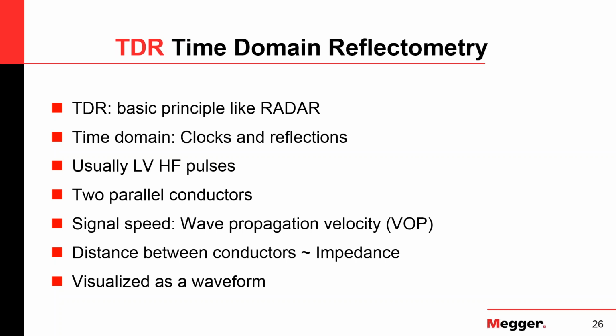So the TDR, by sending down those high frequency signals, will give you an impedance fingerprint of the cable with a low voltage measurement. And today's TDRs are much more evolved than 20, 30 years ago, and they can visualize that trace, which is way more important than just giving you a footage, like a distance, a numerical value.